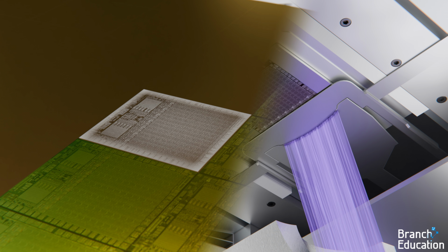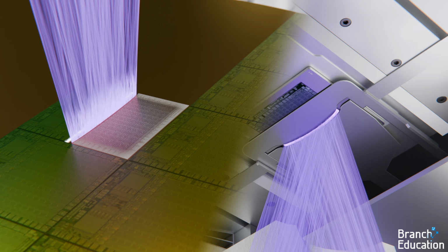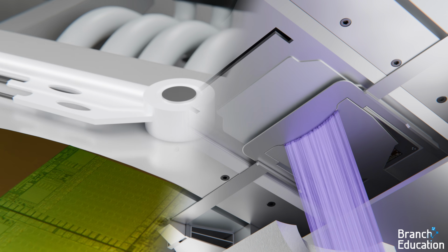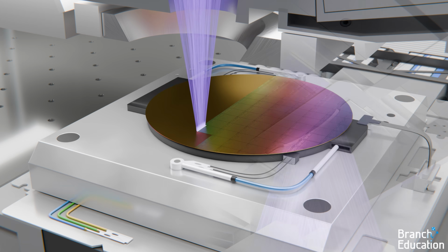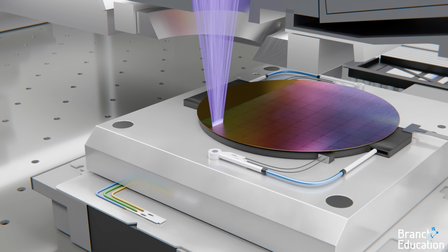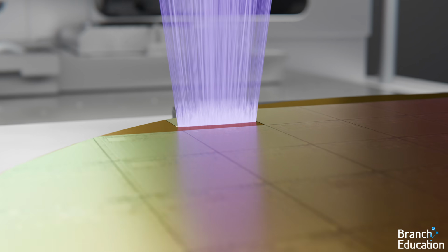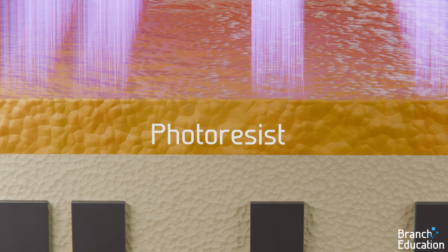Once the wafer stage is positioned to pattern the next microchip, the shutter opens and the wafer stage and reticle stage move in perfect synchrony again. This process repeats until the entire wafer is patterned, taking around 18 seconds in total. So then, what actually happens as EUV light hits the photoresist?